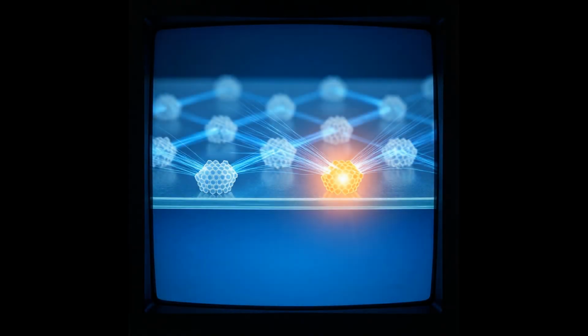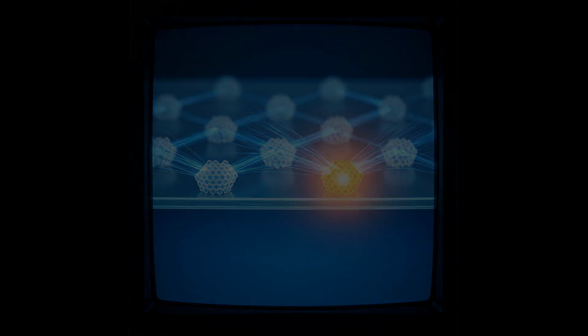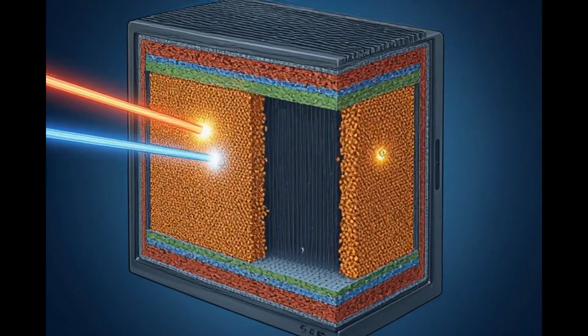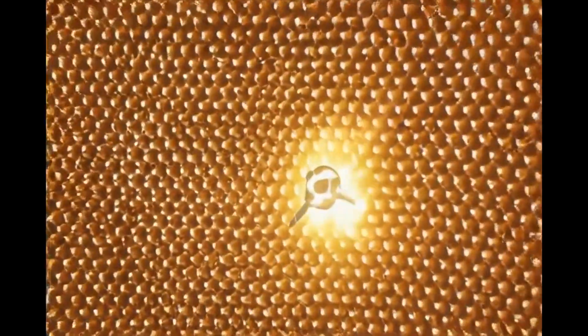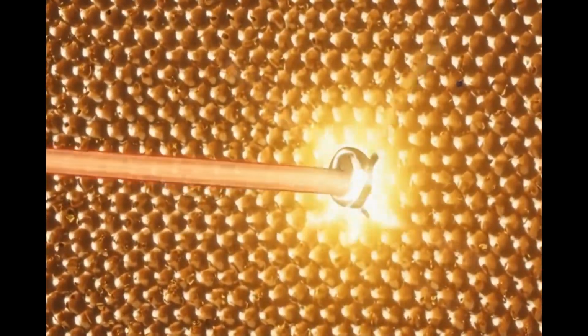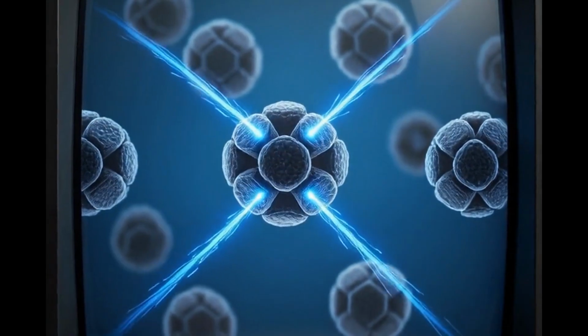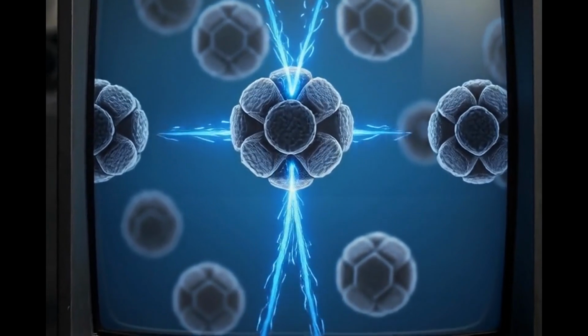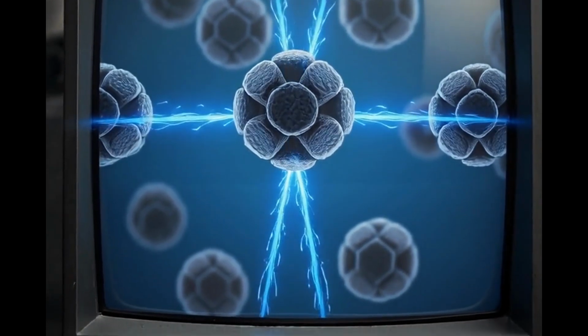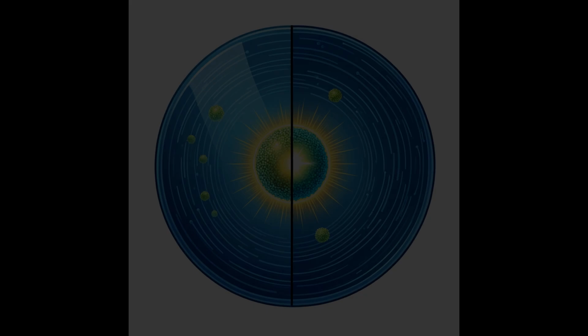During this relaxation process, the excess energy is released as discrete packets of light known as photons. For instance, a copper-doped zinc sulfide grain will emit green light when struck by an electron beam at specific voltages. This precise conversion of kinetic motion into visible radiation creates the bright pixels we perceive on the display. Understanding this atomic interaction sets the stage for analyzing how our eyes integrate these rapid flashes into a continuous image.